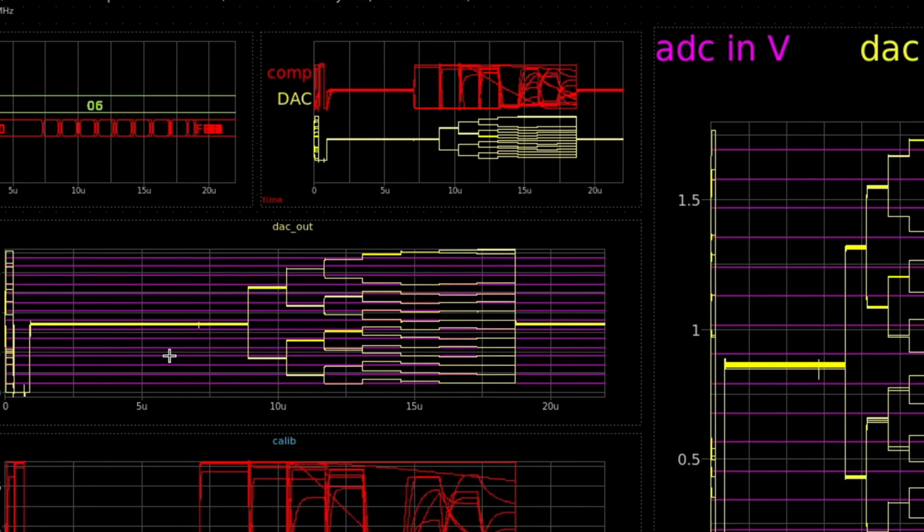When you've got a digital blob like that, you can simulate it entirely in analog land. This is hard, heavy, and slow, but it works the same way as the rest and shows you exactly how things will behave, parasitics and all. Otherwise, you can go the sensible route and leave the digital bits digital using Verilator. This requires more setup and messing around, but then it runs at a decent speed. The results I got from the ADC were using an analog 5 MHz clock and accounting for all the parasitics, just because I at first had trouble getting Verilator to behave, but also because I was curious. It took 16 hours or something, but the results are beautiful to look at.